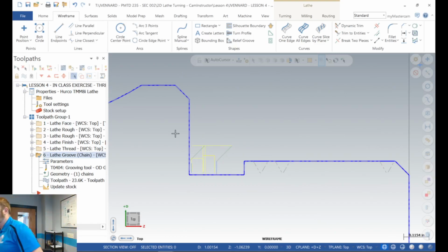So that's one way to get the relief groove to cut just that lower area that you want it to stay in, without all that extra movement. Now guys, I'll also tell you this. If I'm only cutting one part, I don't care if it takes 6 extra seconds to start up there and then work its way down that wall to finish out the groove. It took me longer to go in there and fine tune it than what it would take to do that.